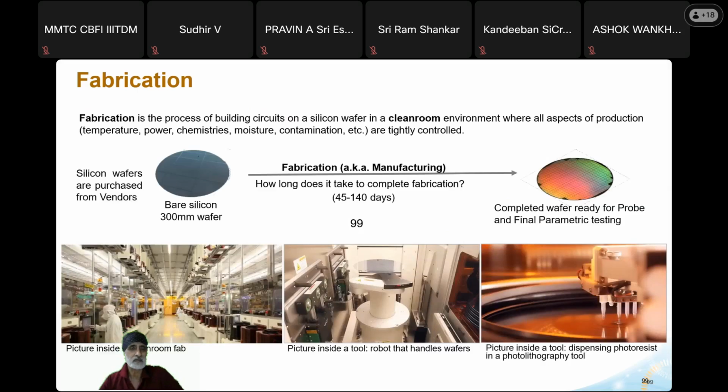So the silicon wafers, bare wafers, there are people who make only wafers. That also is a long process, but they will make wafers only, and the wafer will look like this. I showed this last time also. If you are able to see, this is a plain wafer. This surface is just like a mirror finish. And these are standard, diameter, thickness, everything is standard.